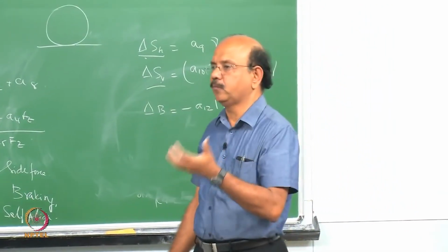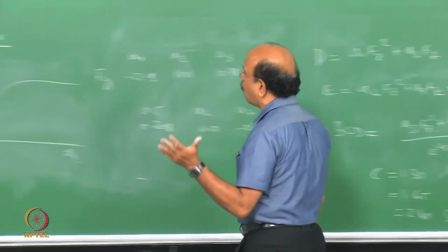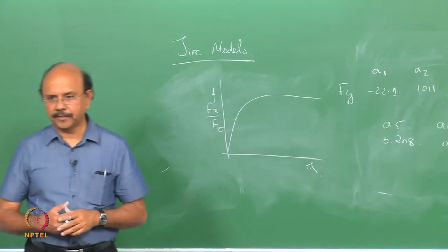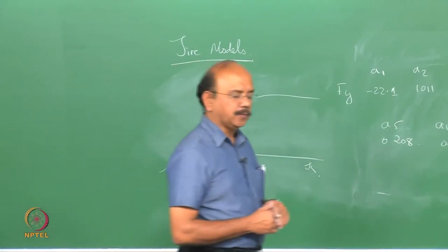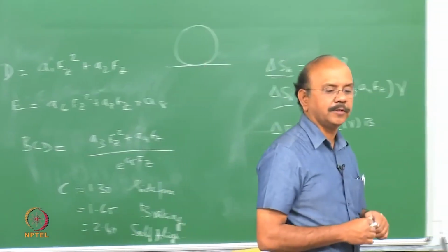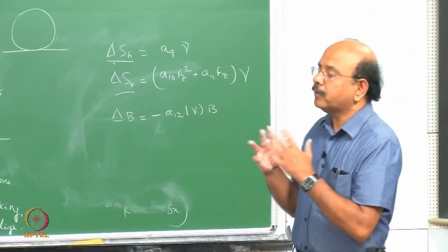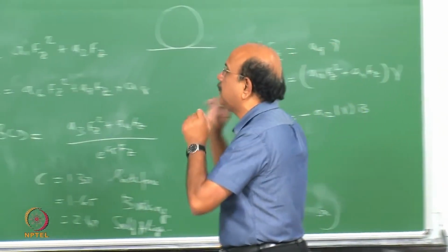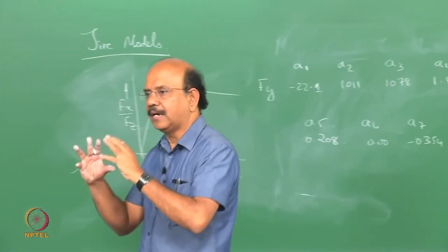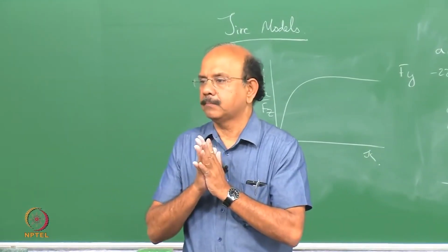Can this curve be like this? There has been a lot of work, as I told you before, as to how actually friction works between the road and the tire. It's a big topic by itself. So this depends not only on the contact pressure, but also on the slip velocity, and so on. If you want to model the tire behavior in a very detailed fashion, then you have to go into those friction models. But all the systems that we have are based on this, right?